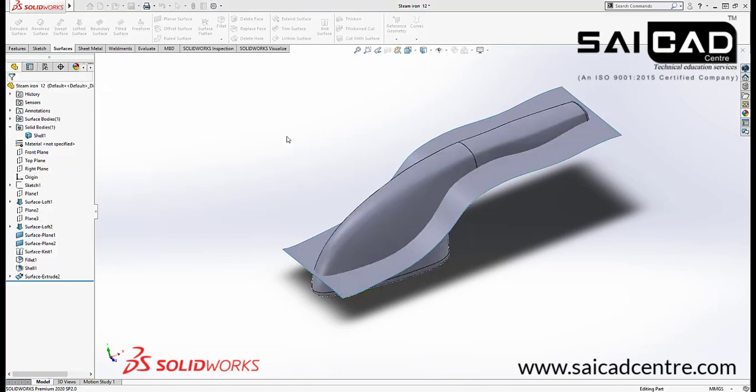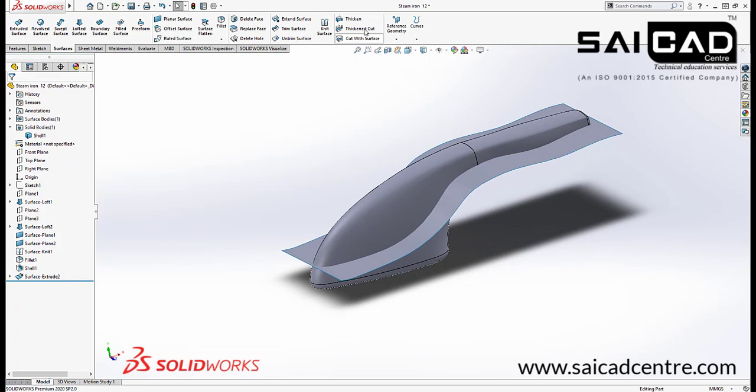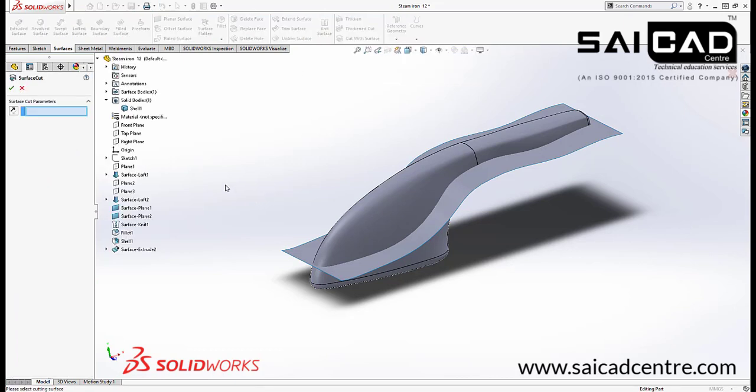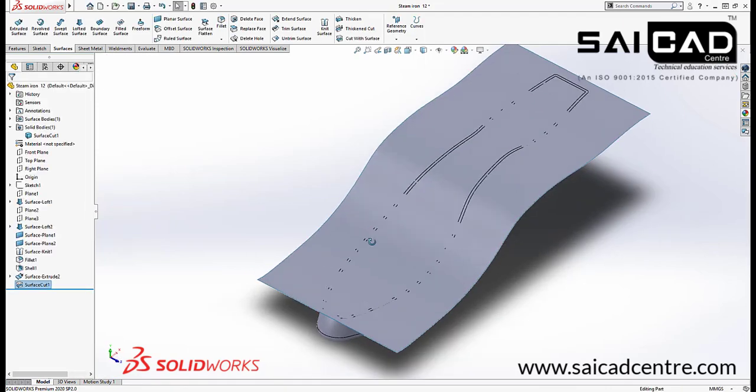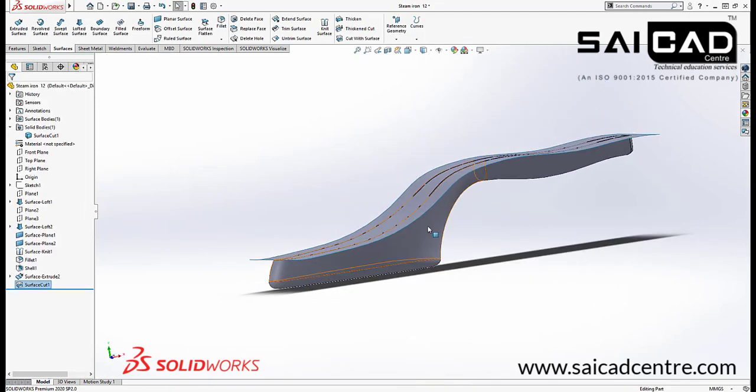If you have some error here, you can see we have the cut with surface option, and thicken cut. If we select cut with surface and select the body from here, select the surface only, it will ask which body you need. Click OK, it will just cut that side and you will just get the other side only.